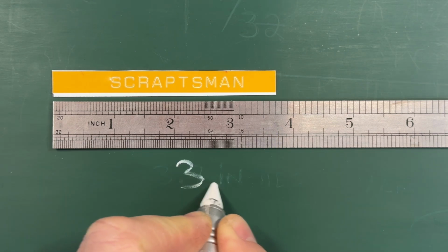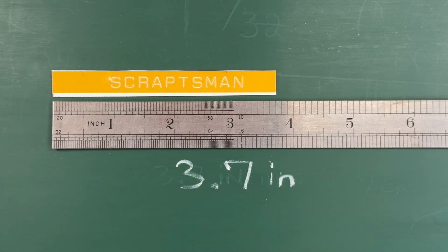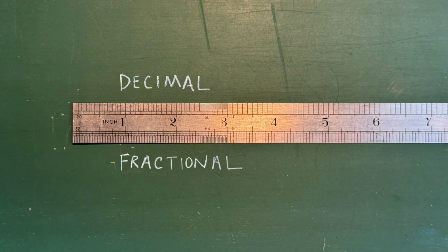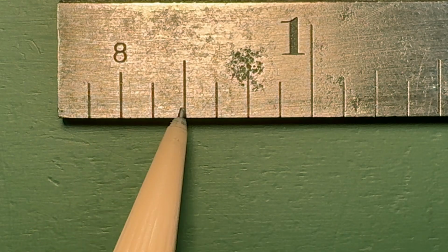Decimal rulers are not as common, but they are out there and can be easily mixed up with the typical fractional graduations. So always acknowledge the tool you are using and its level of graduation before you measure. If the graduation is not printed on the tool, you can always count out each mark and see how many times the inch is divided.